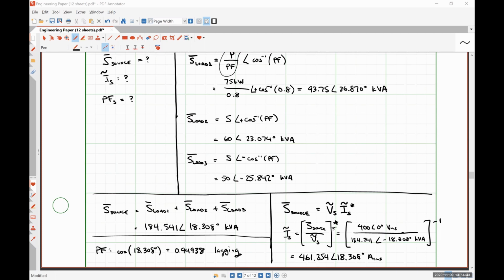It says a voltage source Vs is connected across an 8 ohm resistor. Find the average power absorbed by the resistor if Vs is given as these different functions. There are a multitude of different ways to approach this problem. However, I would argue that finding the effective value of the voltage waveform is going to be the easiest way to go about this. So the effective value for part A is literally just going to be 3 over the square root of 2 because it's a sinusoid.